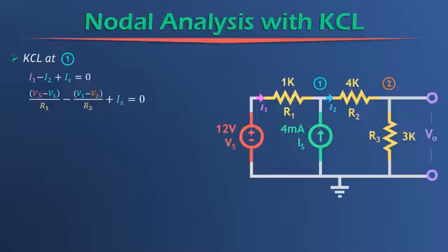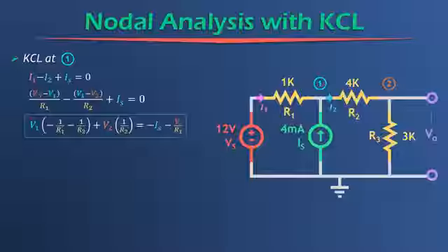And now we can just do some clever algebraic rearranging, and we can get it into a form like this, where we have V1 times some constant plus V2 times some constant. And usually these constants are the R constants for resistance. And then we're going to set that equal to the other constants that we know here. Alright, so just let that be for now. We have an equation with two variables. So in order to solve for both of those variables, we're going to need another equation so that we can get two equations, two variables, and then solve using some method.